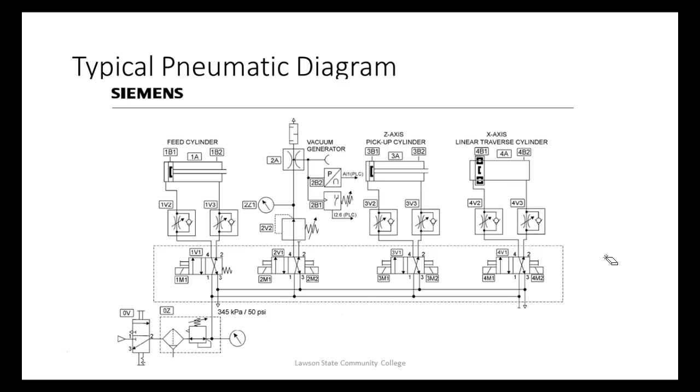But for the force that we're generating, rodless cylinders work real well. These are actually running our gantry robot right here. So that's 2 magnets. So this latches on magnetically. I've seen them use straps coming out. I've seen them use chains coming out. And so they actually move a chain. All the ones we have on our line are magnetic.